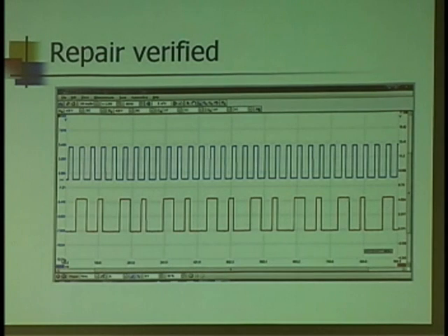The Ford synchronizers, if you look in the TSBs, they actually tell you how to see if you've got a bad synchronizer based on the 3 cam crank sensor that they had. They gave you a pattern waveform to compare to whatever you got. And you could see if it was in time, you know, if that was causing your problem. But if you didn't hook to the same grounds, especially the cam sensor wouldn't look right, because it's one of those AC type sensors, signals that you got. Okay.